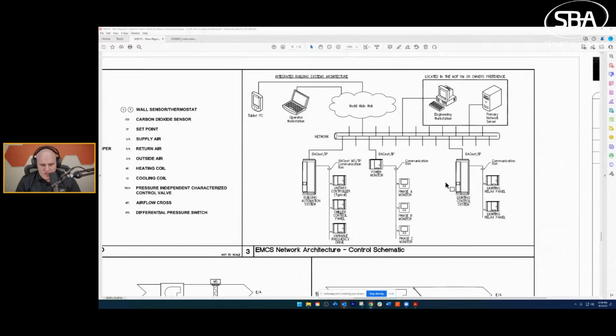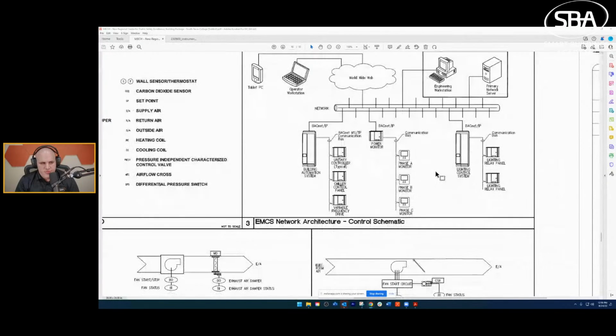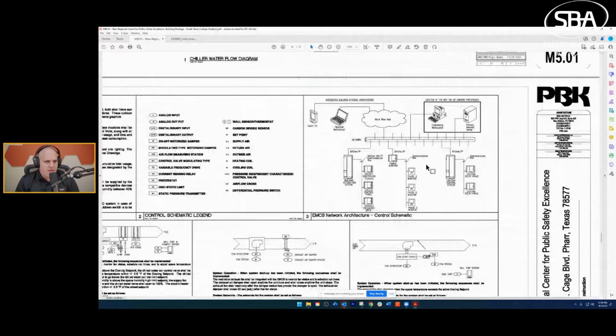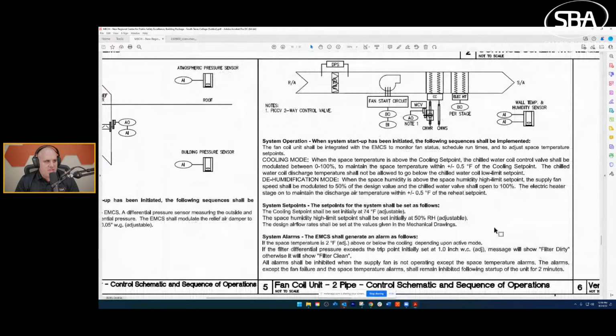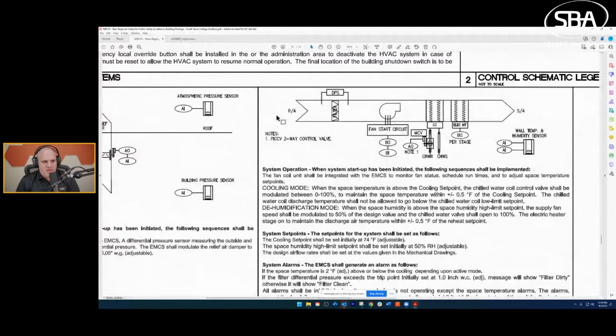The one thing I will caution you on is if you do happen to see, right, a controls schematic, or you see a sequence on a mechanical drawing and you see a controls one line. This is called a one line because if you draw it right, it's one line. And then you have your control devices. This actually calls out like, hey, there's an AO. Hey, there's AIs. Hey, there's BOs. This is still something that I would be careful of because as you start to go and get the equipment submittals and you read through the specification, things may actually be a little different.